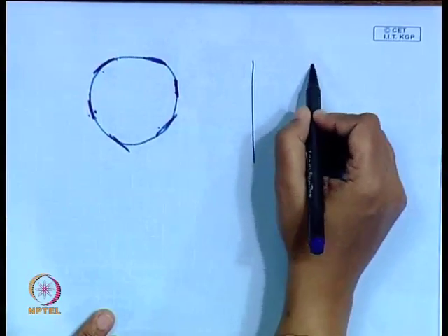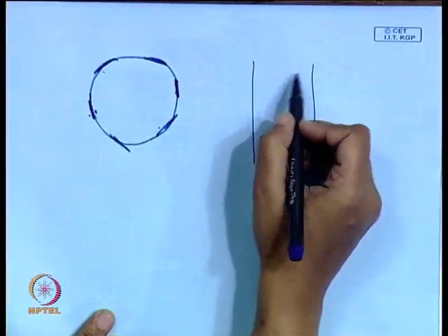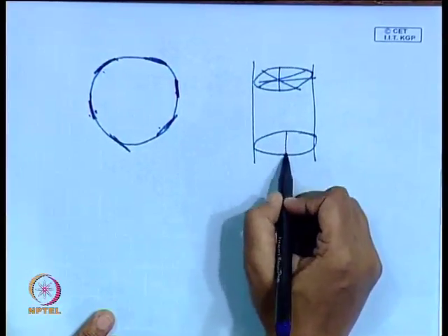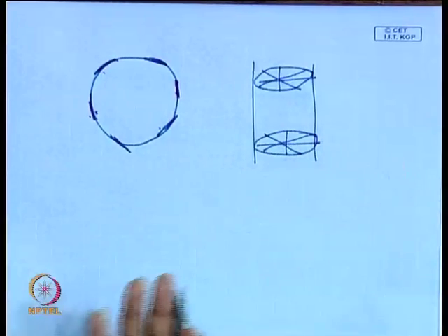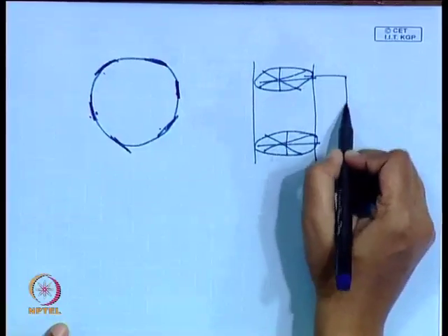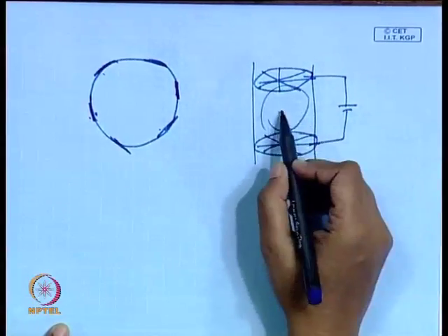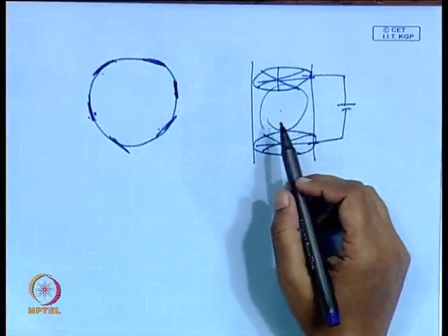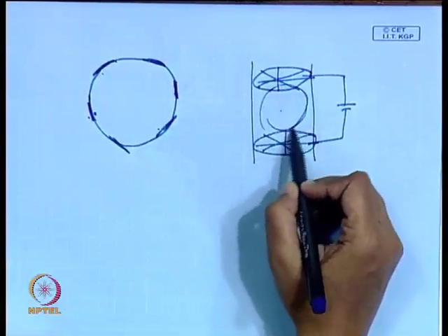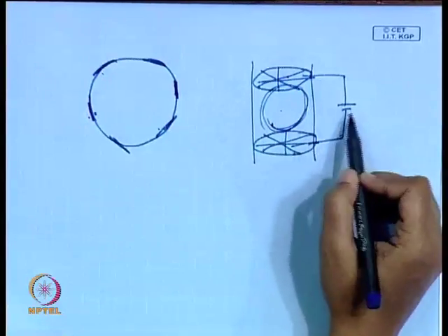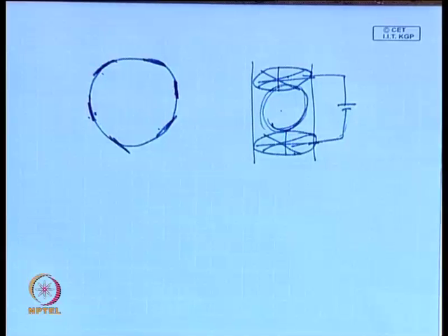Suppose we want to measure the volume average, what will we do? We can just have one particular wire mesh probe here, and one here, just like the strainer through which you strain tea. We can have those on both the ends, and these can be connected to a circuit. This is usually used for bubbly flow, for measuring bubble velocities, etc. Depending upon the two phase mixture here, we can obtain an idea about the volume average void fraction.